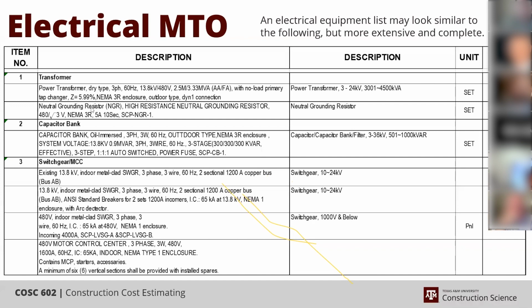If you have multiple transformers, I mean, today I was in a meeting for a hydrogen plant, and it had 14 transformers feeding into the common PDC. Here we're just showing one, so it could grow quite a bit. Depending on how many motors you have, your MCC switchgear, your PDC switchgear, and your MCC starters and cabinets could be quite extensive in this list. Here we're just showing 5, but it does give you an example of what you might encounter.